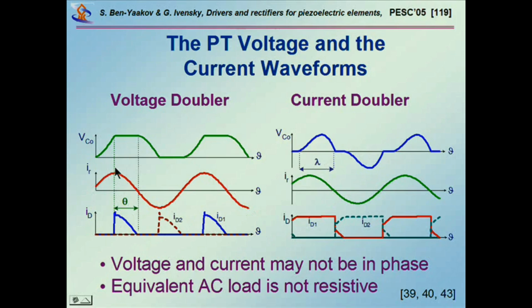Because if the current is sinusoidal, then real power is generated when the voltage is at the first harmonic. All the other harmonics will not generate any real power, because the multiplication of a higher harmonic with this sinusoidal wave has, of course, an integral of 0.